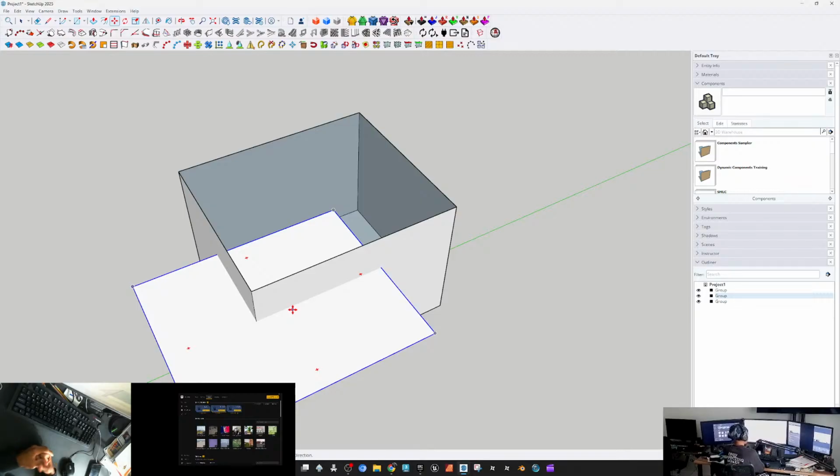So let's say you're drawing a cabinet, and the cabinet's supposed to have cabinet doors on the front, and none of your entities are nested inside of a group. Your cabinet doors will become connected to your cabinetry, and you won't be able to create any sort of dynamic adjustments to, let's say, open or close those cabinet doors or adjust them with ease.